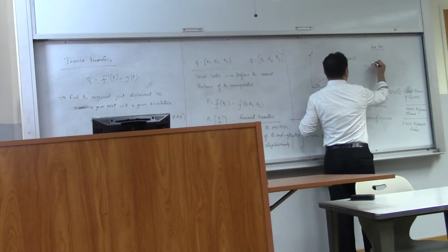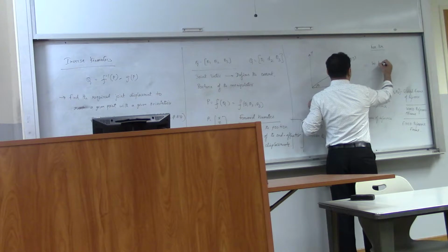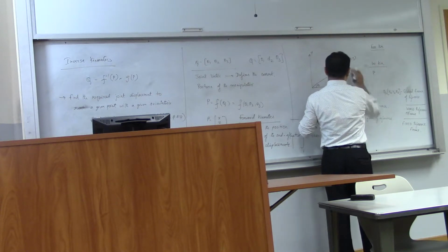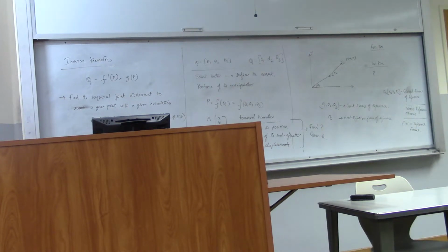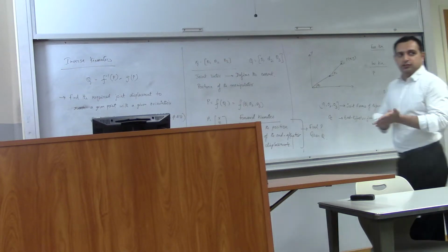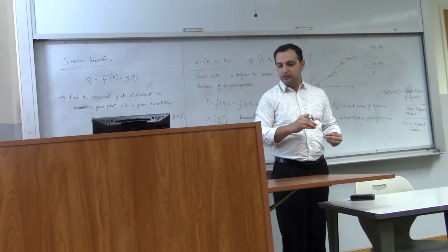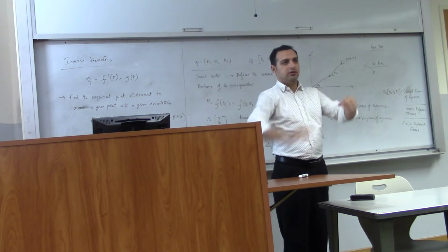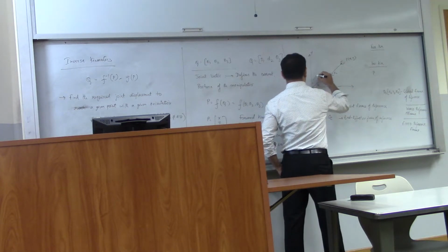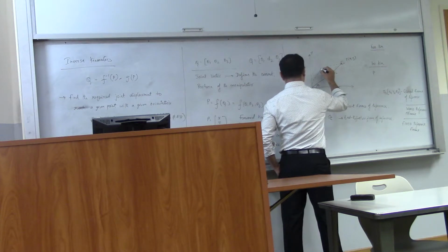But let's take the inverse problem. Inverse kinematics is like this. If I give you P, let's say I want to reach this point, will theta 1, theta 2 be unique? No. How many of you say yes? Unique? Just one? How many of you think no? Why? Because we can reach there by different angles. You can have two different postures, right? So for example, I want to reach this point in space, so I can reach it like this, or I can reach it like this, right? So you can have the same point reached like this.